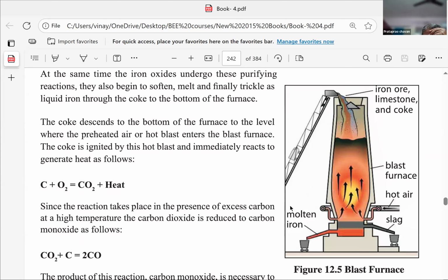Now, as an energy auditor, I am interested in what the exhaust temperature of this gas going out is. Is it 700? If it is 700, it contains a lot of heat. Can I use this? Because unless I use this heat, my furnace efficiency or performance will not improve. Secondly, there are other chances of heat loss. One is, of course, the cover. The enclosure of this blast furnace should be insulated. Otherwise, a lot of heat will radiate to the atmosphere, right?